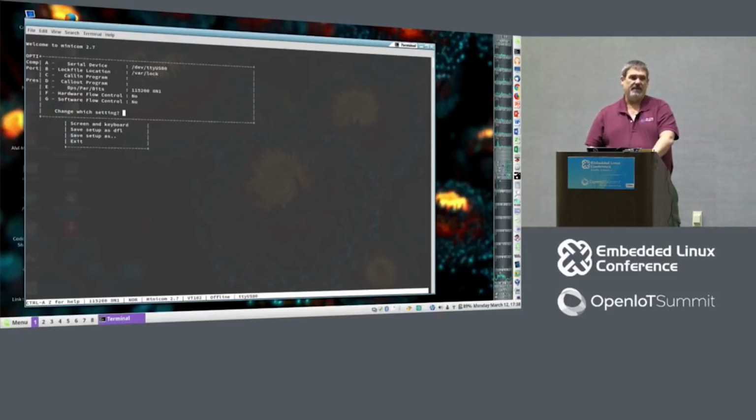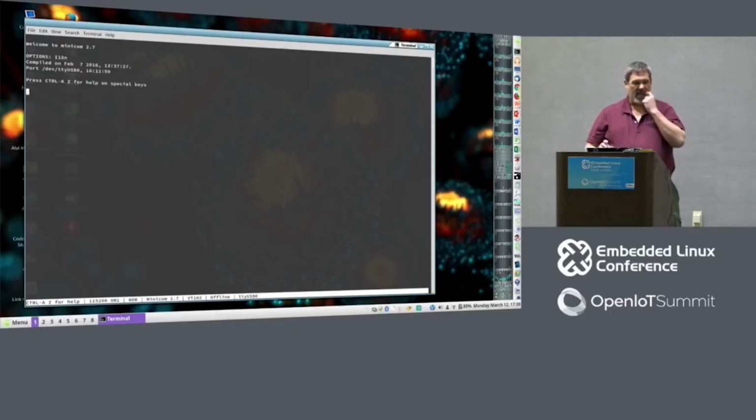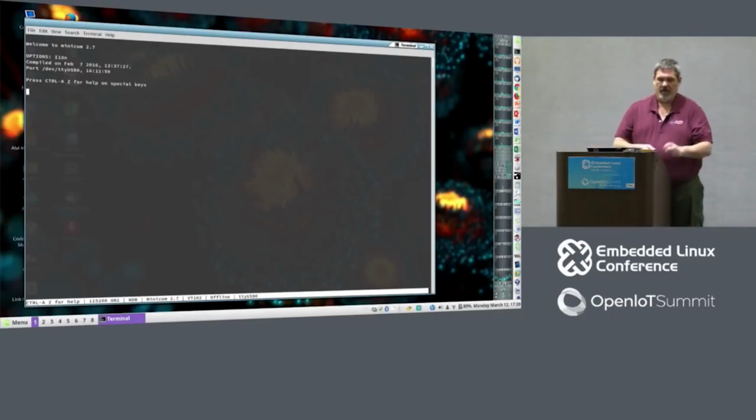That's the other problem that we run into with serial. In most cases, it'll be no parity, 8 data bits, 1 stop bit. But that's not guaranteed. It could be 7 data bits, 1 stop bit, even parity or odd parity. Odd parity turned out to be one that they used a lot in older equipment. So again, look at the signal as it's coming across the scope and see if you can figure out whether you've got start bits and stop bits and how many of those things you have. So let's assume that we're running here, and I'm going to go ahead and power it up and see what happens.